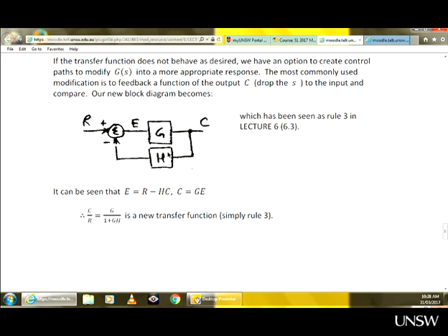So, in other words, it is possible to successfully control a very old, almost dysfunctional system if you have a good sensor. So the sensor has to work well, and the control loop will work well. However, if you have an unreliable sensor, no matter how state-of-the-art a system you have, the control loop will not work as well. So the control system is much more sensitive to changes in H than to changes in G. And that's pretty much all we are saying here.